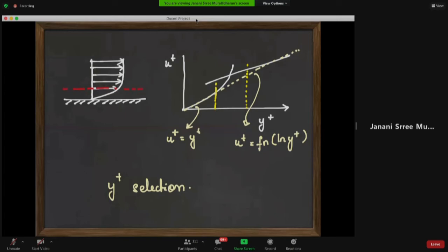based on observations from experiment, the wall function approach typically has observed 3 layers or different trends in the velocity behavior. Okay, right near the wall, y equal to 0 to say y plus equal to 5. I will explain what this y plus is in just a bit. Think of it as a distance for the time being.